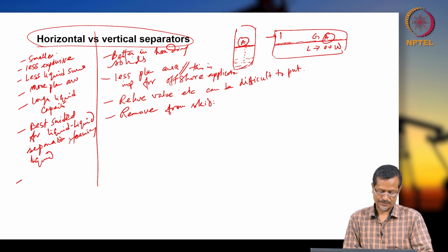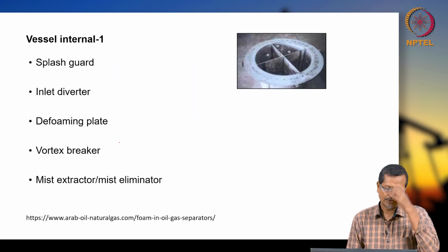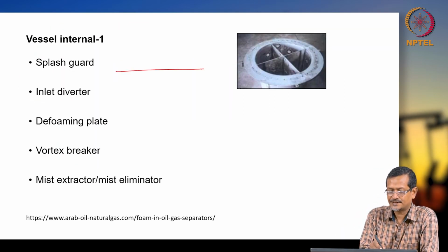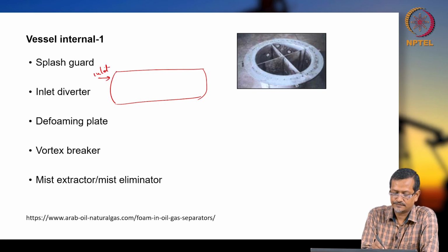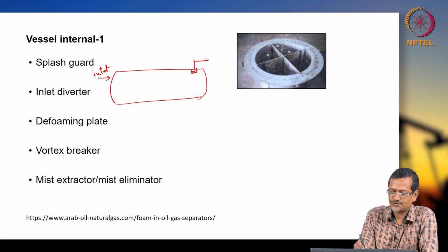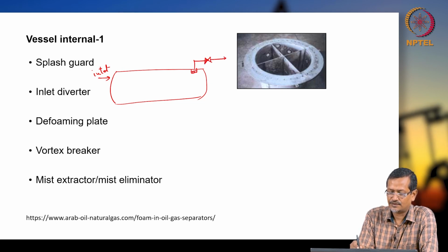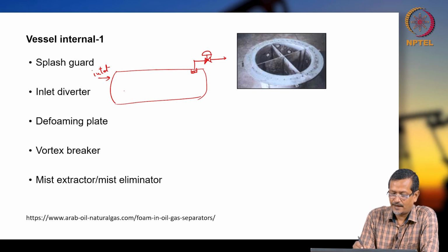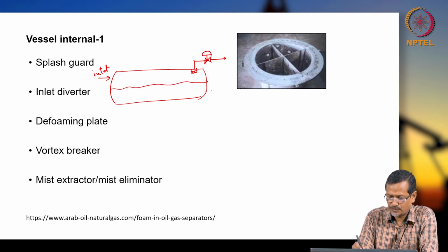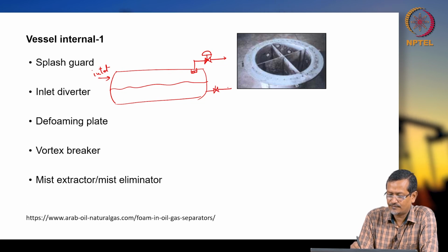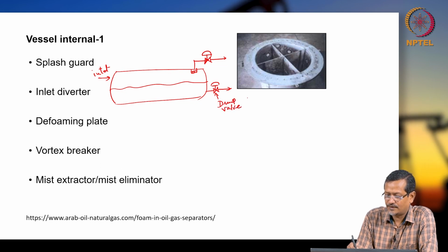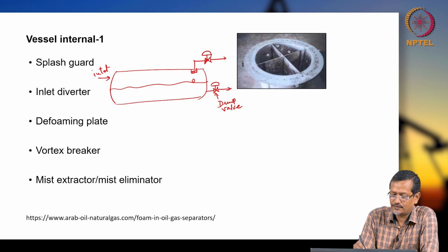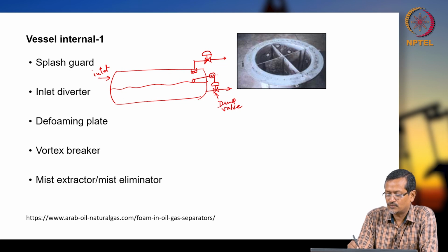Then you can use it. So, this will be better. Okay, so till this time I discussed basically a vessel. It is having inlet flow. I have shown you the mist extractor and your control valve here, and basically I have shown two phase. So, there will be a valve, the dump valve, this is called a dump valve, and it will be controlled by a level controller. So, it will be like this, LC, level controller.